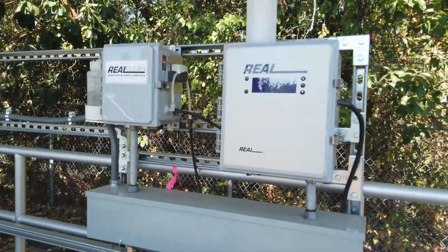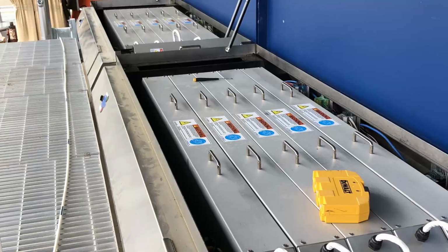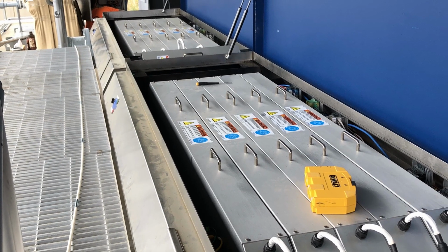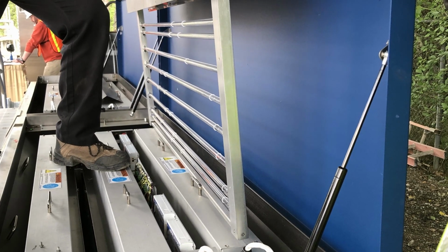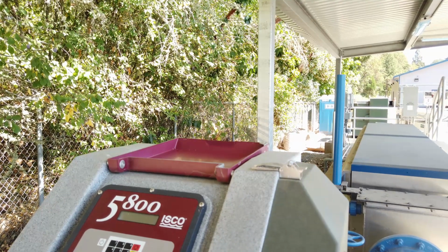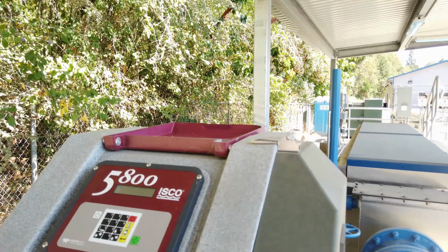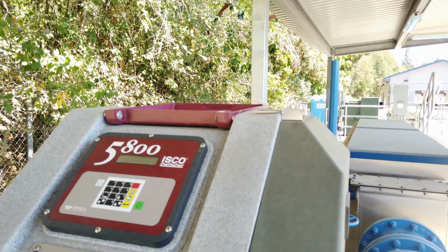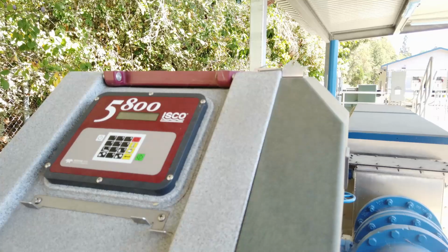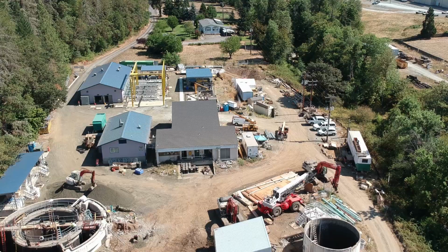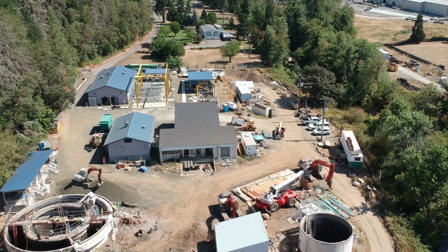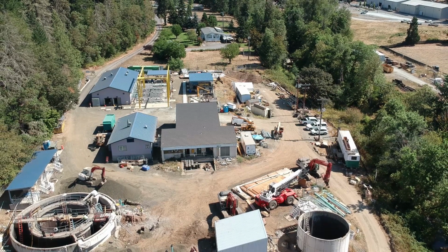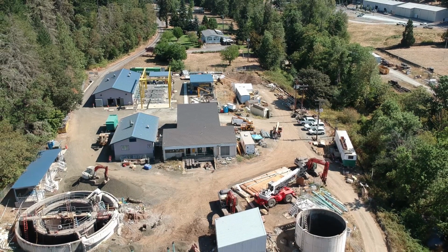Also included in the UV system is a temperature probe that continuously monitors the effluent temperature and logs it for discharge monitor reporting. An automatic sampler is included that pulls effluent after the UV system. The sampler is configured for flow pacing mode. At this point, the effluent is ready for discharge to the South Umpqua River and flows by gravity through a non-potable water tank and then to the outfall.